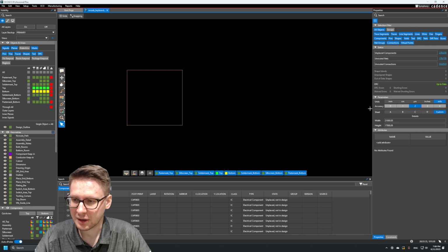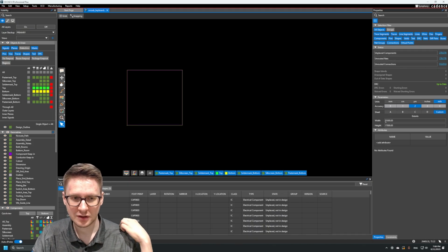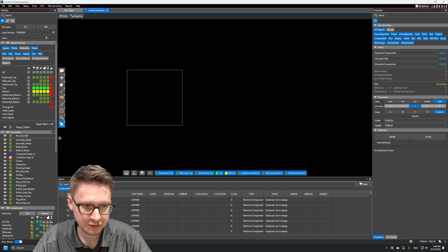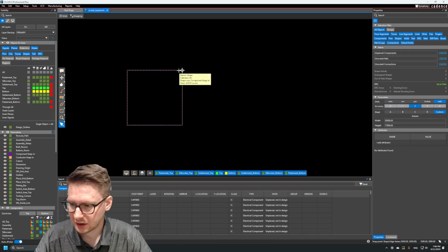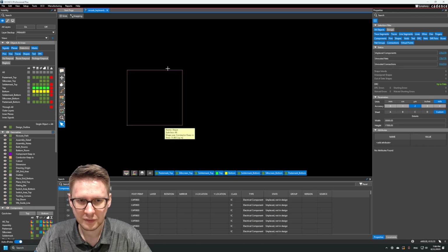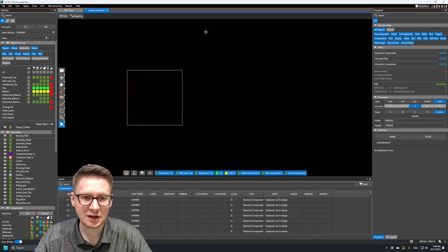But in my design parameters here, the width of my drawing is only 21 inches. So I need to extend this. If this left side is minus 7.5 inches, I need to extend this at least 15.5 plus 7.5, or to be safe, I'm just going to call this 30 inches wide. And a height of 17 is actually just fine, because if this is 0 here, and this is 6, and this is minus 5, that's plenty of space in the y direction.